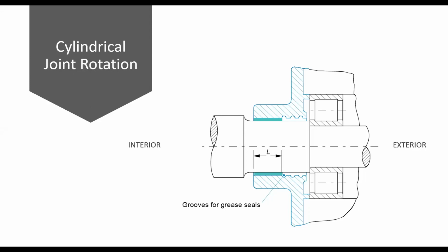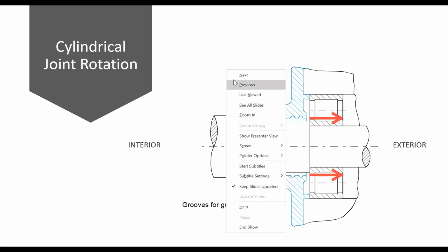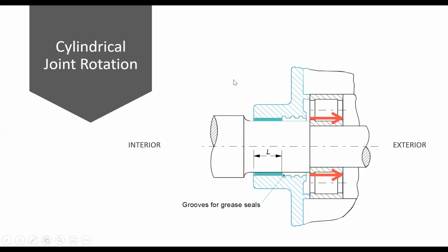Obviously, on an electric motor, you have rotating parts. That is what electric motors are all about. If you didn't have a shaft on it, you would just have a box full of electricity, wouldn't you? Obviously, because the shaft has to rotate, there needs to be a larger gap. The flame path on this illustration is just before the bearing. The bearing housing, the bearing casing, is never a flame path. It will always be either before the bearing or after the bearing.